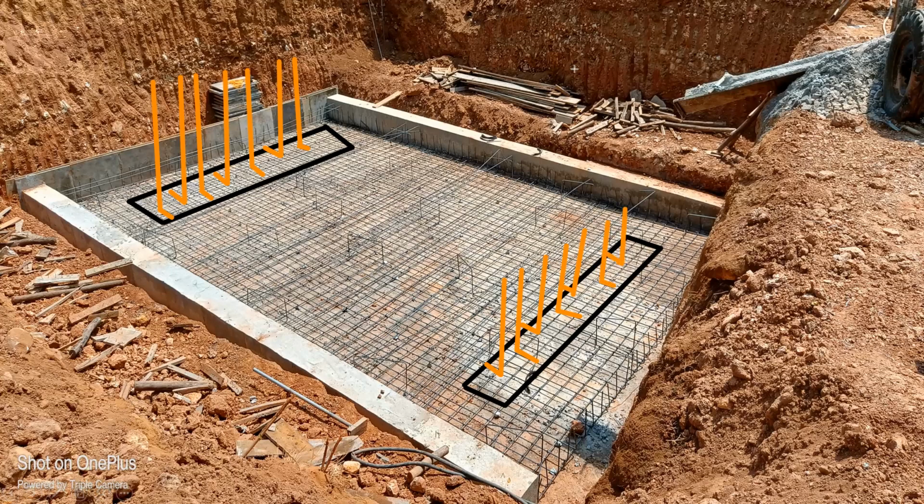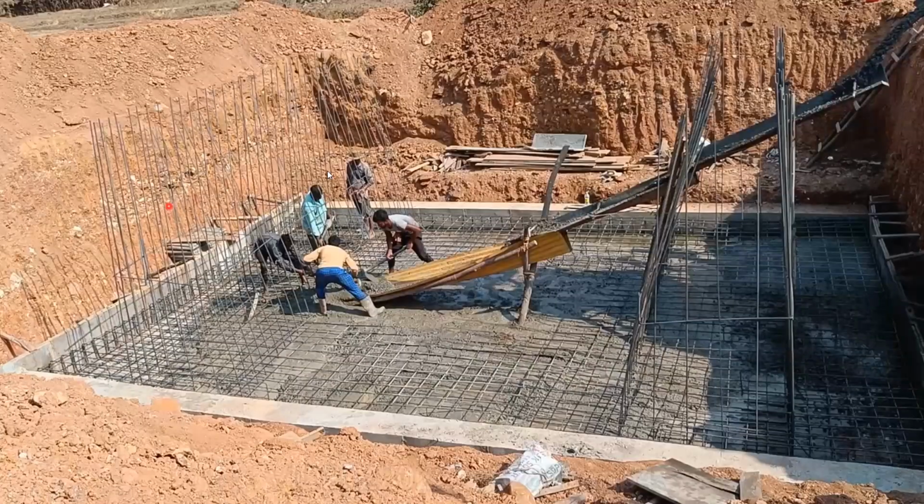So once you are done with that, next you see here how we have done. You can see the same thing. See, this is what they have done. Okay, it's an abutment reinforcement what we have. So this is how we have done. We have placed it here. You can see the L shape, whatever I explained, see how the L has been given. They brought a bar, and you can see. So again, how much this L should come? It's actually a development length. It will be written in the drawing. Okay. Based on that, we are supposed to do the execution. So this is done, and then we are going to pour the concrete.